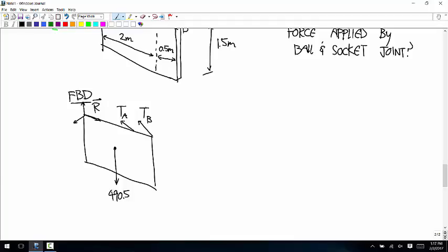We know that we're going to get 6 equations from Newton's laws. So that's something to keep your eye on. What we need is for one of those equations from Newton's laws to end up being either a linear combination of other equations or a degenerate equation like 0 equals 0. Okay? If one of our equations doesn't go away, then we can't solve this. Because we can only solve a system of 5 equations for 5 variables.